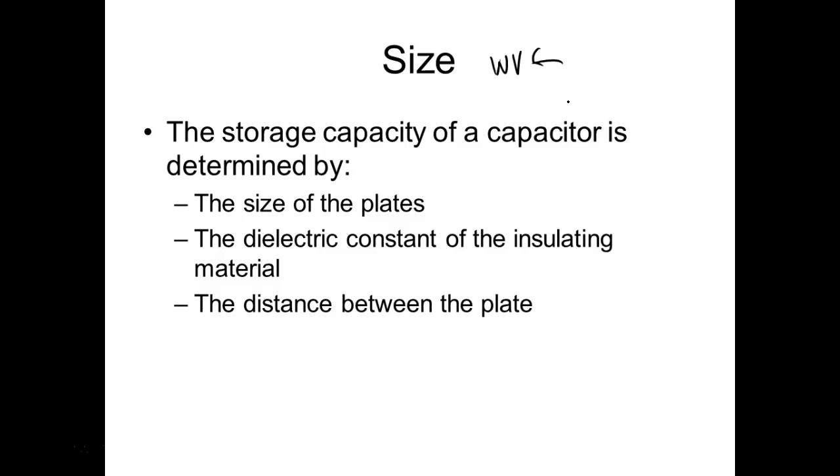But sometimes they pop. A lot of your electrolytics have one end sealed with a rubber head, and it'll pop that rubber head out on you. If you ever see a capacitor that has popped out, then you need to throw that away. And you can check these things with an ohmmeter. You can watch them charge, except for the little bitty ones. The problem with the little bitty ones is they charge so fast.